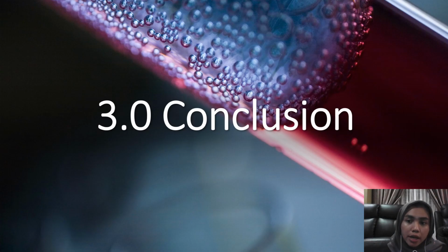As a conclusion, there are four manufacturing processes involved to manufacture this traditional string relaxed chair, which is sand casting, non-metal forming, which is by using direct extrusion. Third is the metal forming process by using indirect extrusion. And last but not least is the joining process, which is using a mechanical fastener by using bolt and nut.